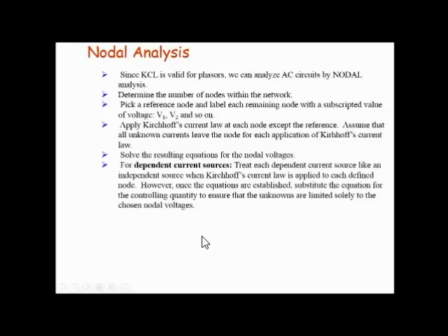First of all, we will start with nodal analysis. Since KCL is valid for phasors, we can analyze these AC circuits by nodal analysis also. We have to determine the number of nodes within a network, pick a reference node and label each node with a subscripted value of voltage, V1, V2 and so on.